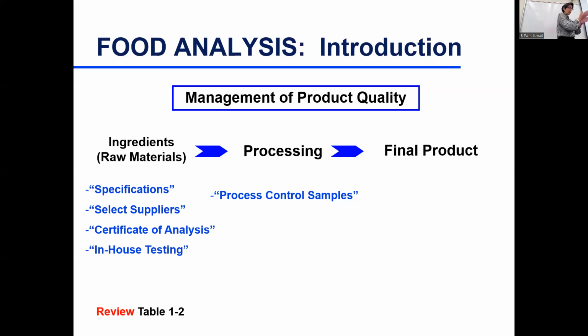So I will check the ash content, which would be an indication if the flour is completely refined or partially refined or still a whole flour. So I would do certain checks. Sometimes I have process control samples that I would test alongside the samples that I would pull online to do certain measurements.